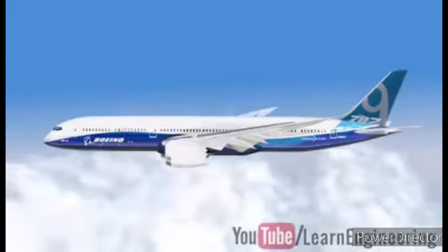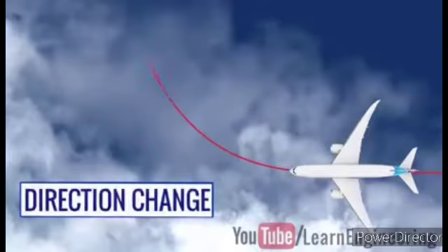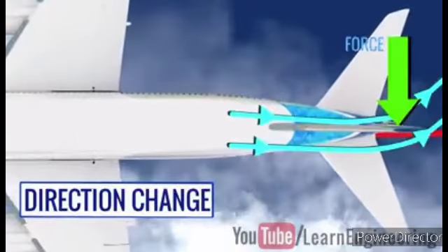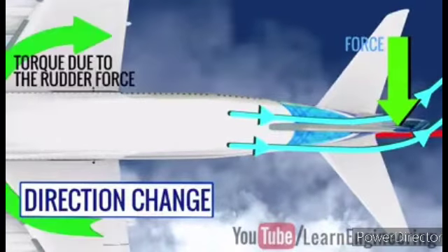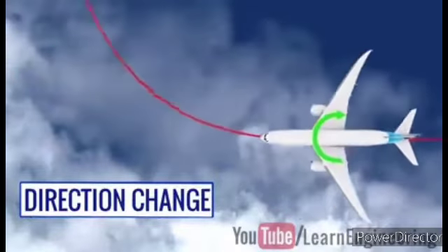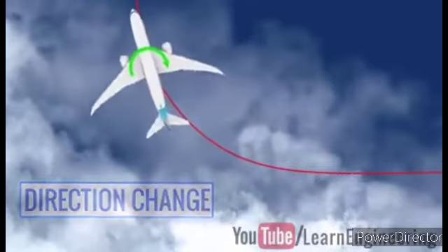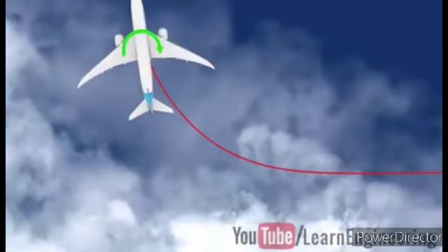How does an airplane change direction? You might think that just by adjusting the rudder, you would be able to do this. The rudder produces a horizontal force, and this force can turn the airplane. However, such a direct change in direction will cause discomfort to passengers, and it is not a practical method.